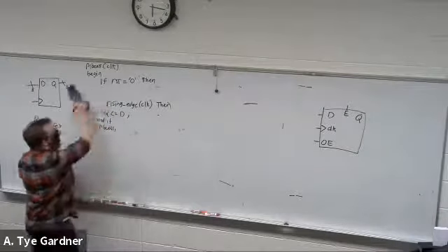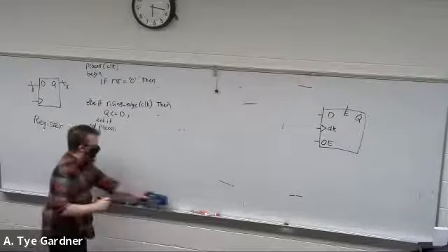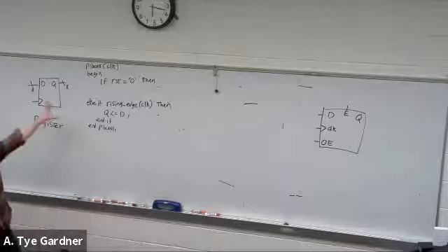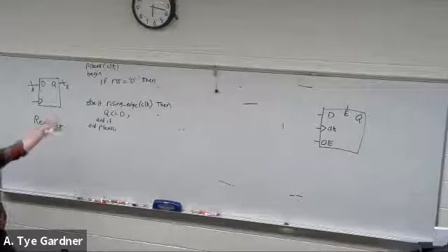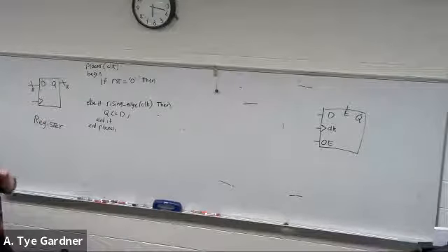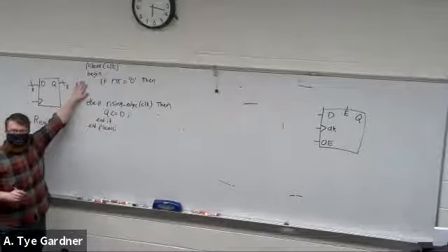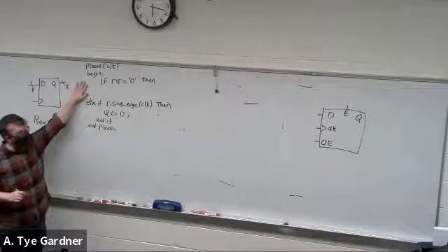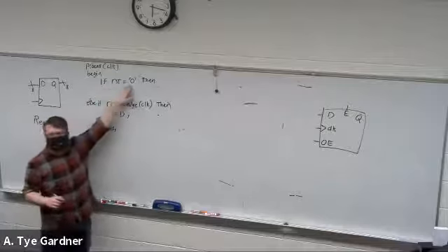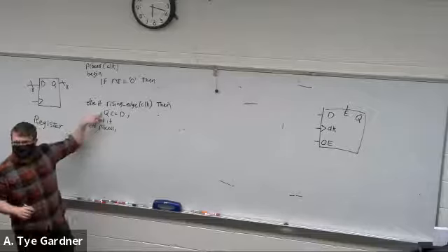All right, that's kind of squished in there. Else if. All right, if reset is equal to 0, then, else if rising edge of clock, then. In the back, is this an active high or active low reset? Active low, because if reset is 0, then we're going to do something other than assign Q, right?